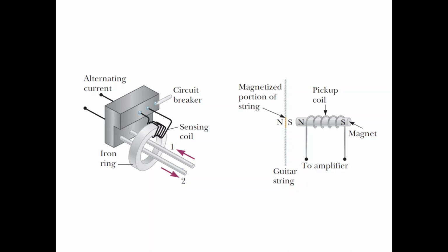In this metal core, there is no change of magnetic flux because these currents compensate each other's contribution to the magnetic field. However, if there is some emergency and part of the electric current is flowing through the person to the ground, there will be a small difference between these two currents. That difference will result in a magnetic field which is not compensated anymore, because part of the current will be going from the circuit to the ground within the building.